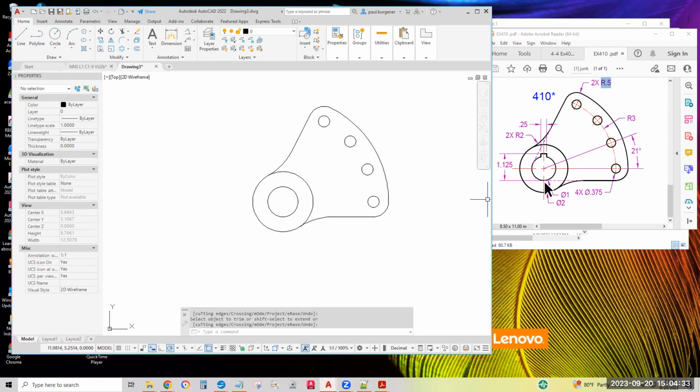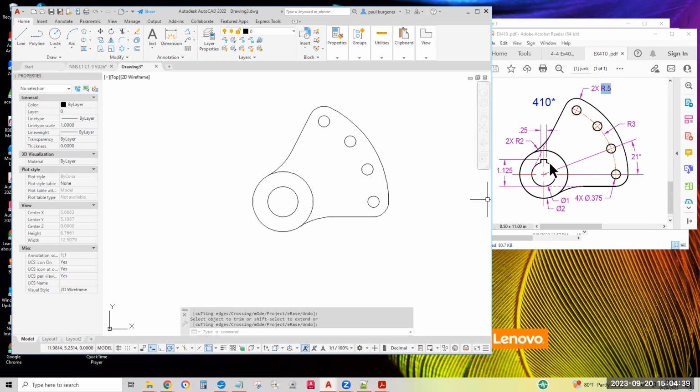Notice that keyways are dimensioned from the bottom of the shaft hole. Some textbooks carelessly dimension them by the height of the teeth, the depth from that corner there. But the inspectors will put a tool in to measure from the bottom of the shaft hole to the top of the keyway.